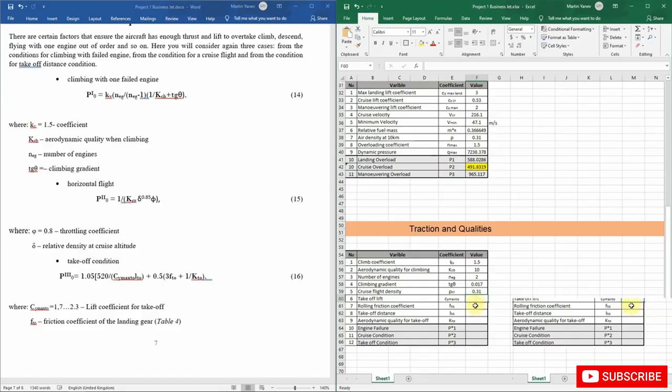The takeoff lift we're going to estimate a bit later, because now I think we can estimate the climbing with one engine failed, and we can also estimate the horizontal flight traction coefficient. So let's see the first equation. This is equal to 1.5 multiplied by the number of engines, which is 2, divided by, again, the number of engines, which is 2, minus 1. And this shows how our aircraft is going to behave when one engine is off.